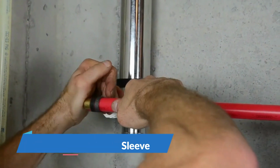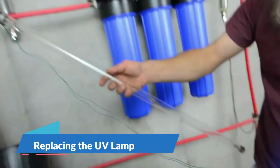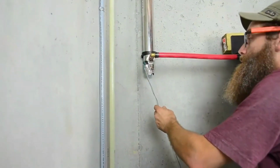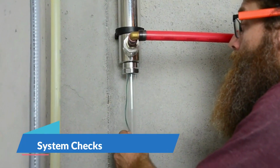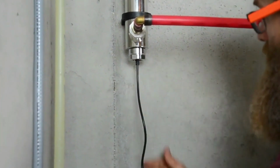Cleaning the quartz sleeve. Regular cleaning is necessary to remove any mineral buildup or debris that could block UV light from reaching the water. Replacing the UV lamp. UV lamps do not burn out like regular bulbs but gradually lose their UV output. Typically, a lamp needs replacing every 12 months depending on usage. System checks. Routine checks of the entire system, including the pre-filtration system and all electrical connections, ensure optimal performance.